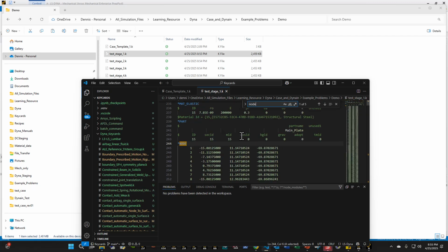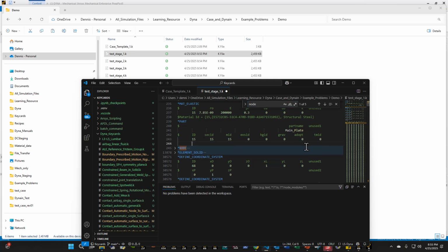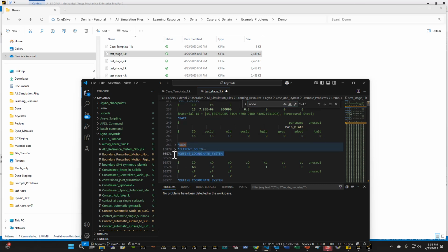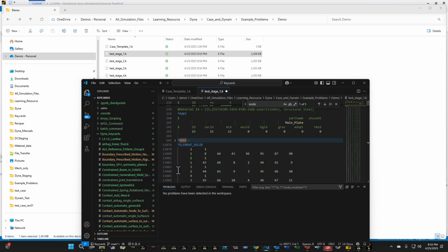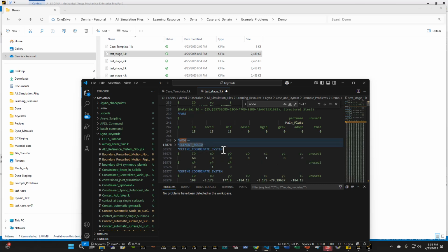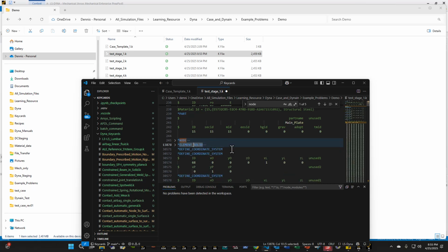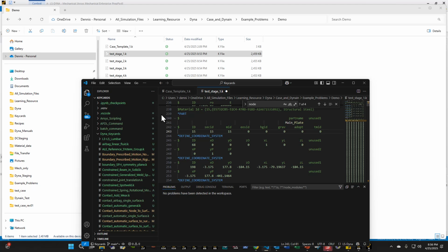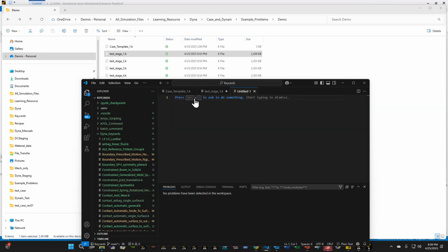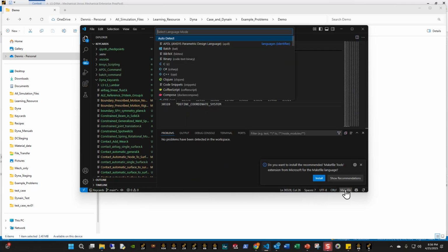What we want to do next is separate the nodes and element data from the input file. Because the nodes and elements represent the geometry of the entire model, I want to separate the geometry out from the entire model and paste it into a separate file called test.geo. So let's generate a new file. I'm going to copy this over and call this file LS-DYNA.